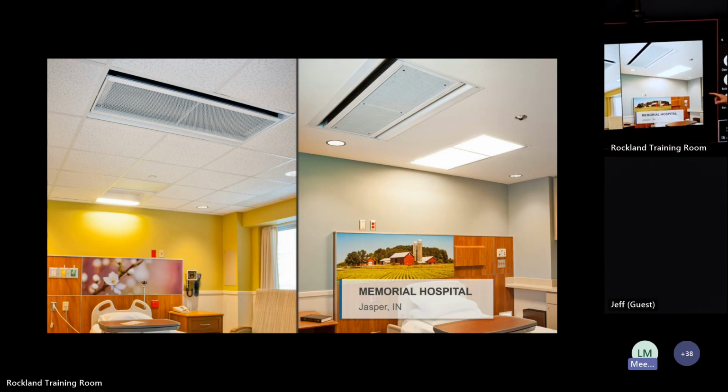But first, before getting to ASHRAE requirements, you can see that you've got different orientations of the chilled beam within the patient bed. There is a preference to having the chilled beam on the right side, where you're discharging away from the headboard and kind of covering the window glass area on the right side. So that's a really sort of, I'd say, optimized location. You can see though that there's lights directly above the patient bed, which are required, so it's offset the chilled beam location. This one on the right, you can see the perf is a little bit different than the one on the left.